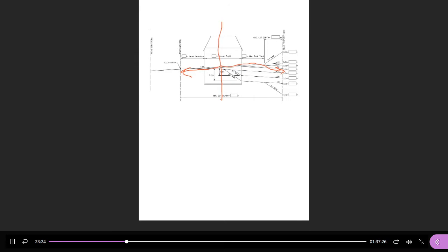So if it's a simple split, it means you have a gentle slope to the front and a gentle slope toward the back. If the elevation at the front of the house and the back of the house are similar, are compatible, then we have a simple split draining lot. So this is called a simple split. And you still have some water going to the front, some water going to the back.